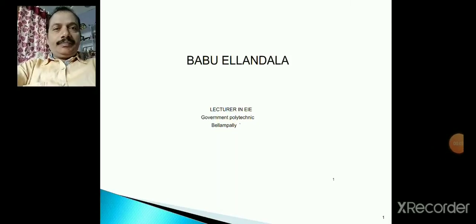So we are discussing the design of sequential circuits. In that we have already discussed registers, shift registers, and after that we have discussed counters. In the counters there are two types: asynchronous counters and synchronous counters. Asynchronous counters receive the main clock in the first stage only. The succeeding flip-flops take previous outputs as clock input. So that is the asynchronous counter. That means the clock signal is not applied simultaneously to all the flip-flops.